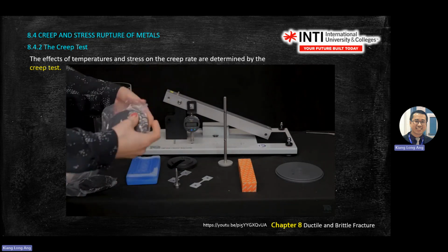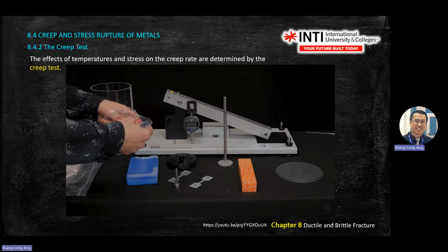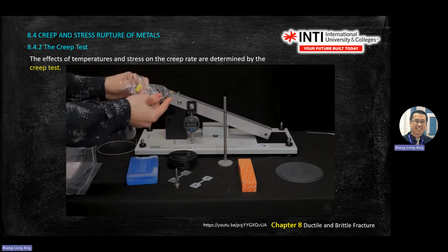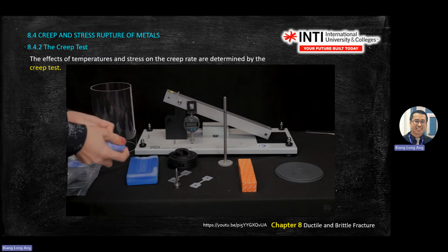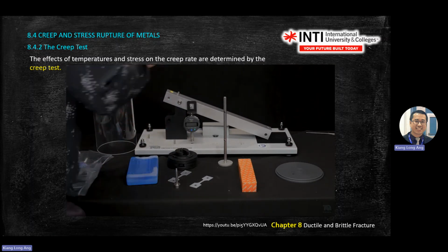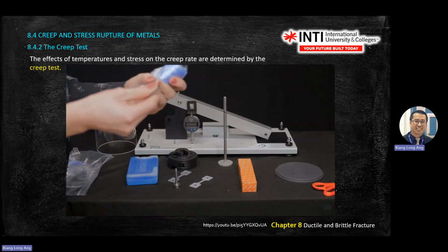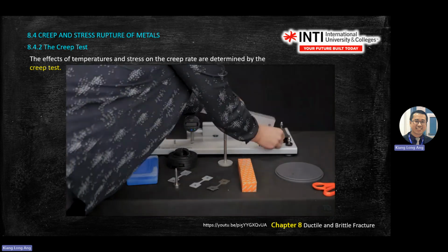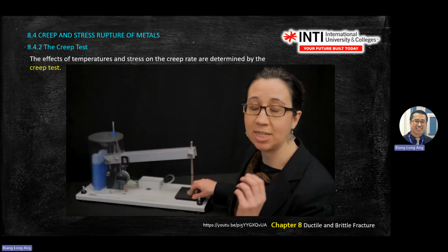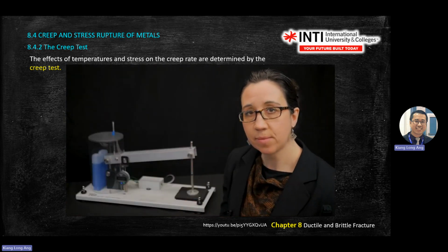on top of the weight hanger using the set of weights supplied. I'll show you how all this is done shortly when we look at one of the experiments. All of this is mounted on a base plate that is labelled with the effective mass of the arm. Just below the weight hanger on the base plate, there is a rubber mat to reduce the impact energy of the falling weight hanger when a specimen fractures.